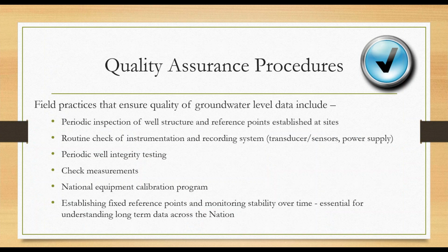Some of the quality assurance procedures that we have in the field to ensure the quality of our data include periodic inspections of the well structure and reference points established at the site. Reference points are important for consistency and to put the data into context. So I will talk about that a little bit more in a few minutes. We have routine checks of our instrumentation. Again, when you show up at the site, there are checks that you should do, but also we have a national equipment calibration program. We have a policy for well integrity testing. I'll talk about that in a moment too.